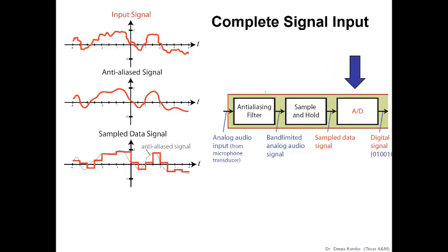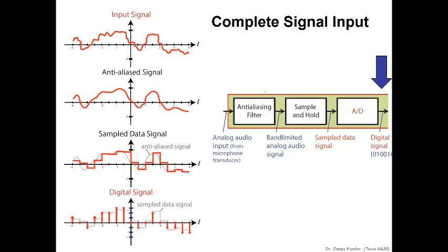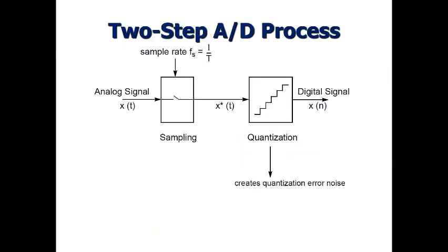There's another step, though, that after the signal's being held, we have to actually, through some mechanism, figure out how to convert the voltage level of our input signal that's being held to a binary number of some kind, a digital signal. And how you do that depends on the style and architecture of the A to D converter that you're using. So, again, we can break that up into a couple of processes.